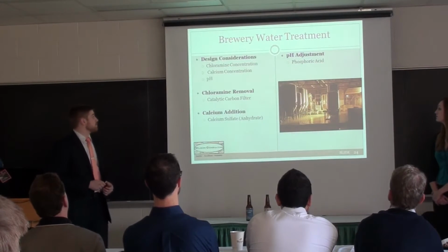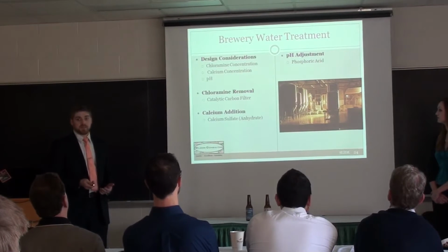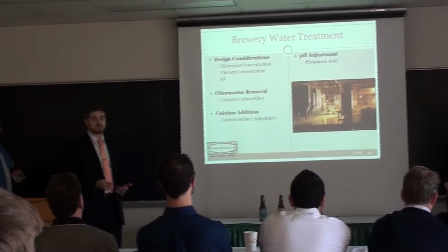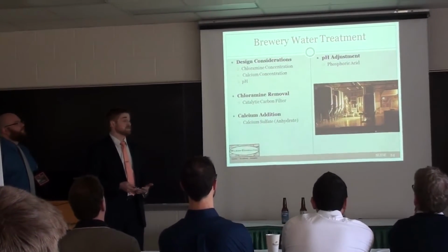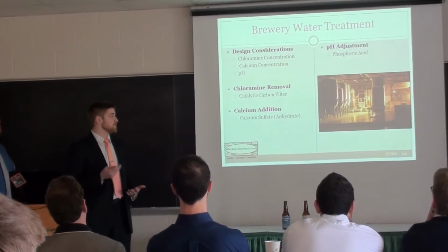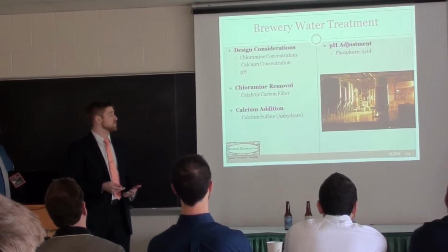So the considerations for the design of the initial water treatment prior to usage in the brewery: the chloramine concentration was too high, the calcium concentration was too low, and the pH was also too high. So we needed to design a system to address all of those issues.